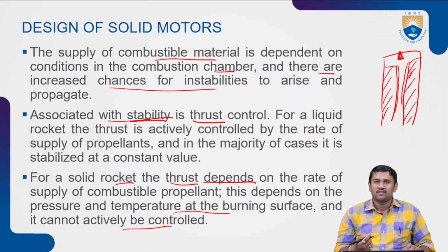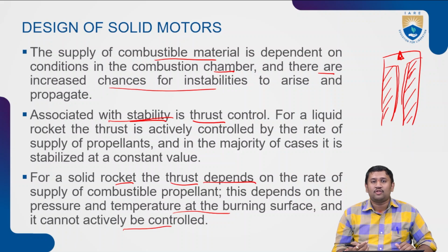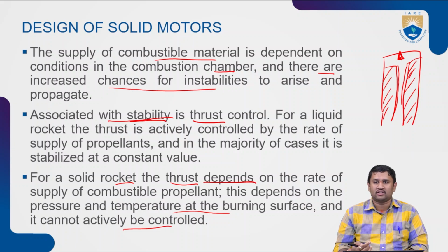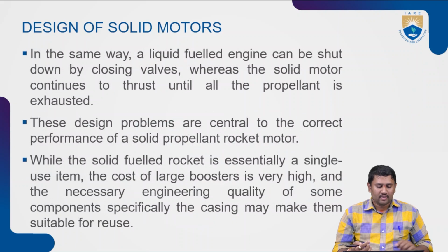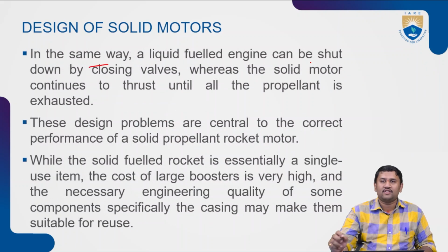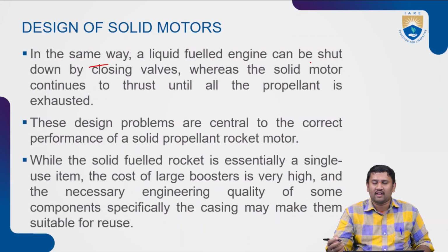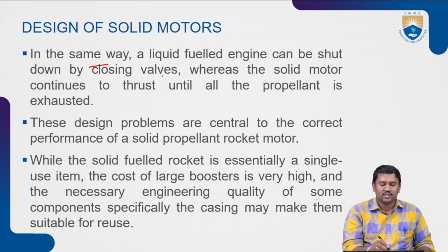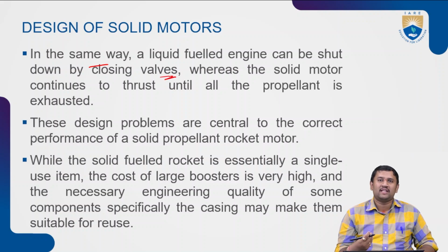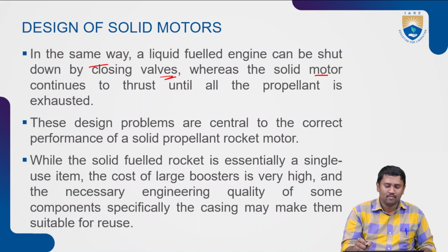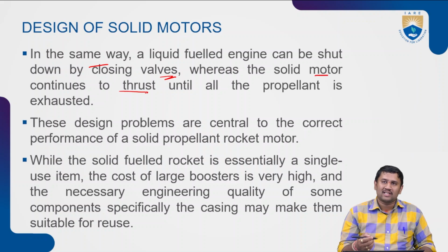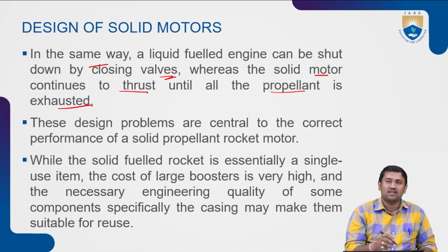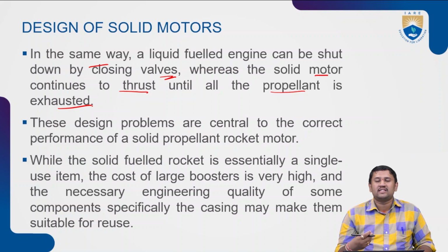Now, what happens in comparison to both? The liquid propellant rocket motors are more stable, or more controllable, than solid rockets. In the same way, liquid fuel engines can be shut down, as we have discussed, by closing the valves that supply the propellant, whereas a solid motor continues to thrust until the propellant is exhausted, unless there is no propellant left inside the casing.